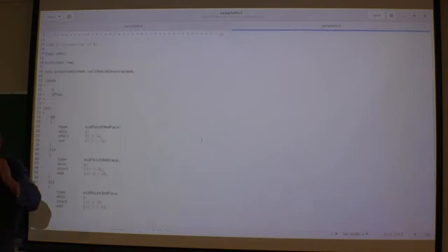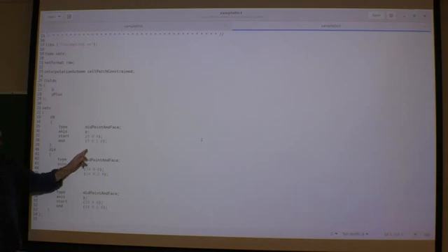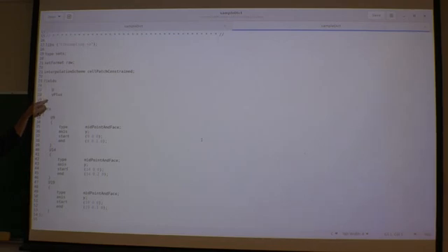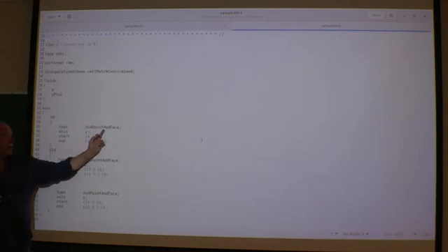So for instance here, I wanted the velocity profiles at 3 different locations. After 9 meters, 14 meters, and 19 meters, for instance. And I loaded in y and y plus. Here again, I have to create this field before I can execute this, whereas normally it doesn't have y plus, so you have to create that one first. So these two is what I wanted. And then you see what I chose here. I chose midpoint and phase.